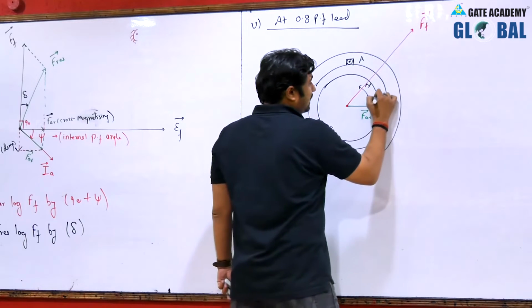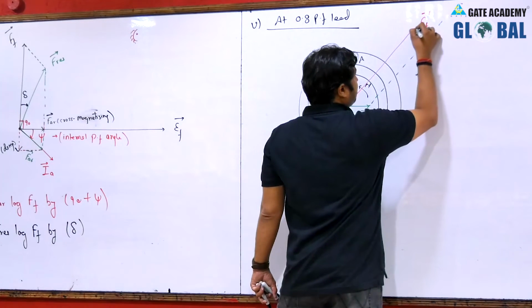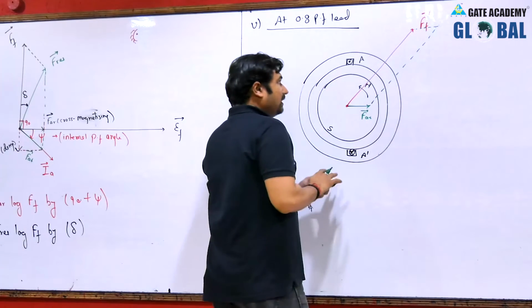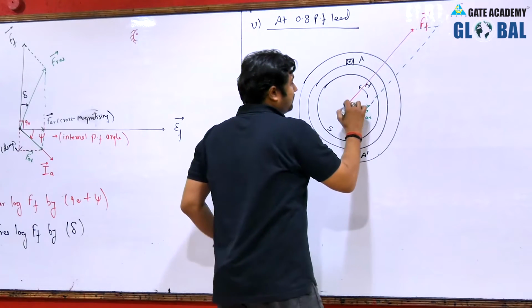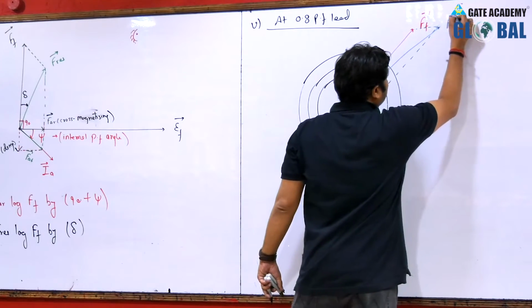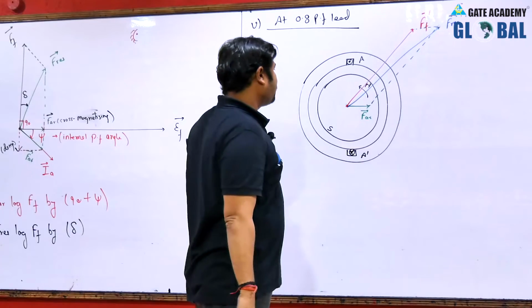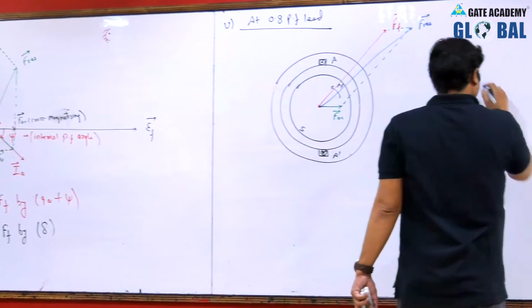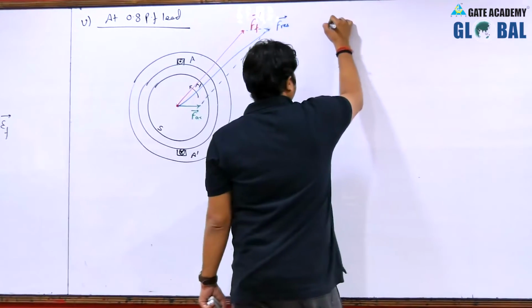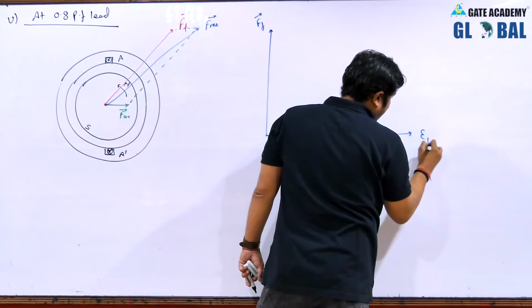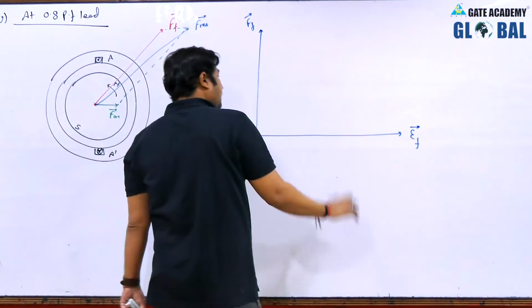So, this armature MMF and field MMF, if we take the phasor sum of these two, then the resultant MMF seems to be more than the field MMF. Is it okay? Now, it can be understood in a better way, as you can take FF as a reference. So, if FF is taken as a reference, then induced EMF EF is 90 degree lagging to FF.